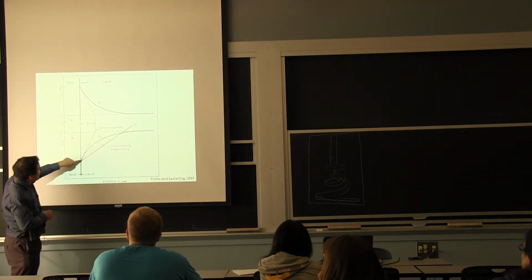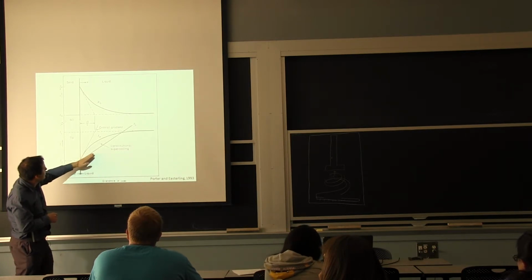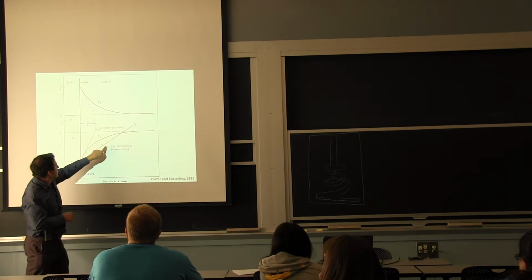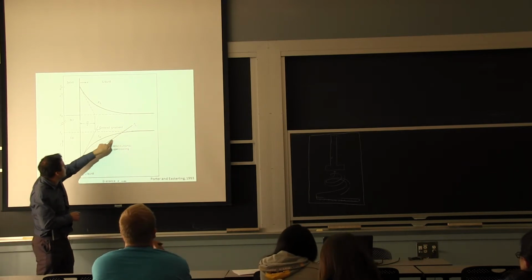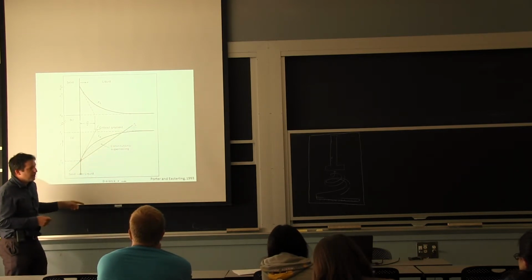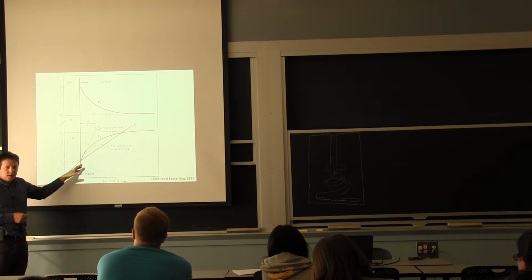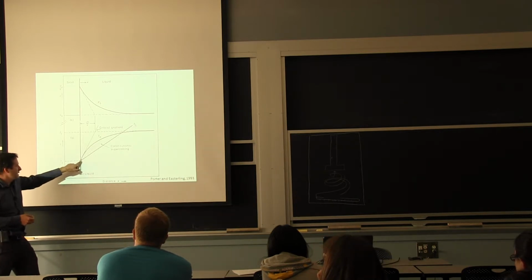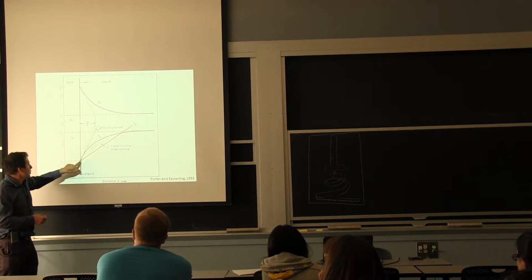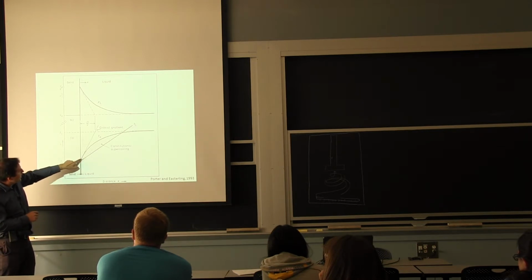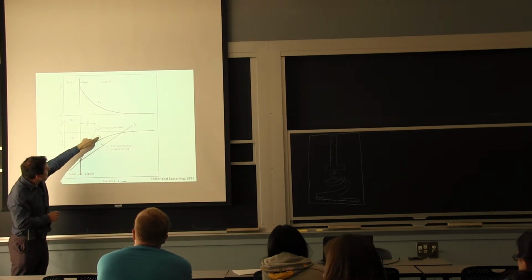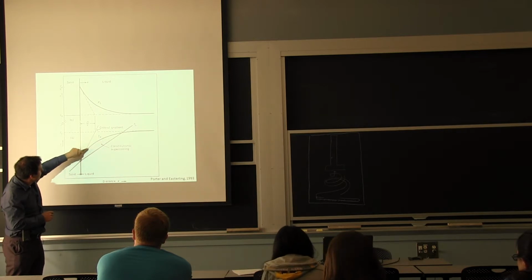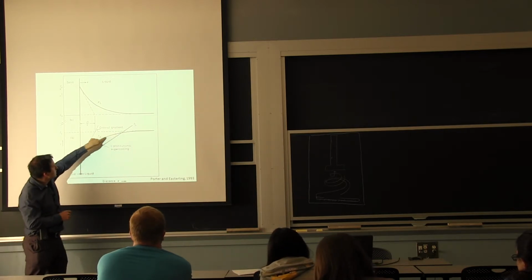If you move ahead here, you can have a situation so the thermal gradient, that's the temperature of the liquid here, tells you is based on heat transfer. So we're putting it here as a straight line. The heat keeps going towards the mold, and we assume we're in quasi-steady state. So it's not too bad of an approximation. At the same time, what we have here is the temperature of equilibrium for that solidification process.